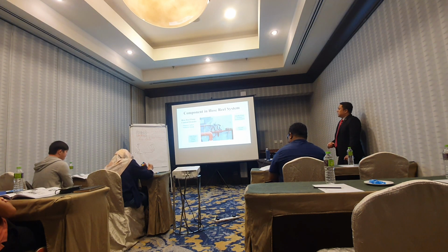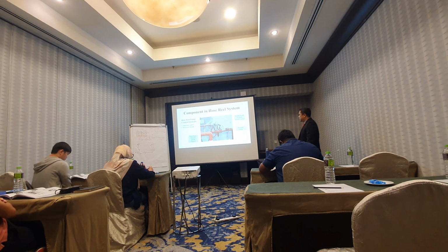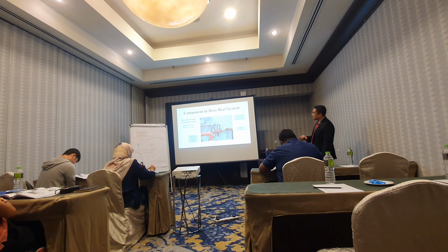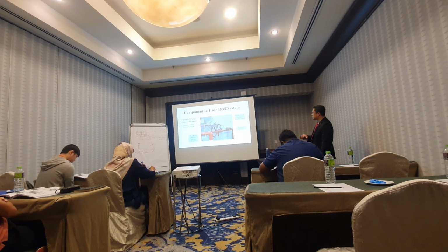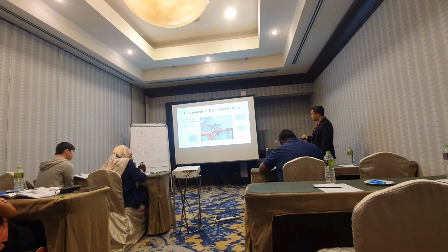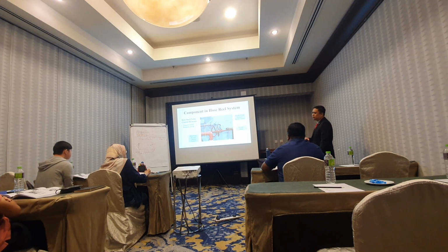Alright, okay. This is the fire control element. Dan yang ni we can see in the pump house lah. There are pressure gauge, there are standby pressure switch here. This pressure switch are controlling the one duty pump and the other standby pump lah. Kalau pressure drop up to 60 and more than 80, 60 dia akan turun trigger the other pump lah.